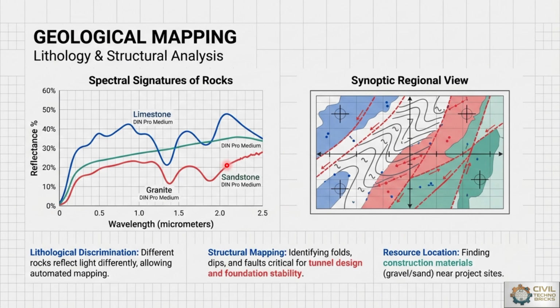So here remote sensing helps to identify geological structures such as faults, lineaments, folds, fractures, rock formations, and many more geological components. These features are most important for foundation design, tunnel construction, dam site investigation, slope stability, and many more studies. Now satellite imagery supports preliminary geological mapping before detailed field investigation is followed.